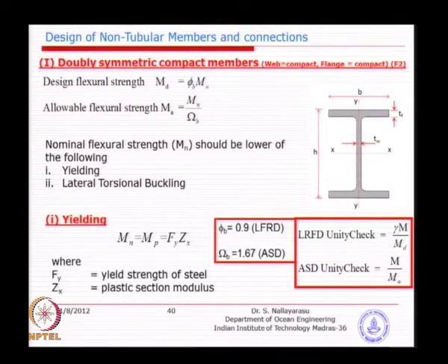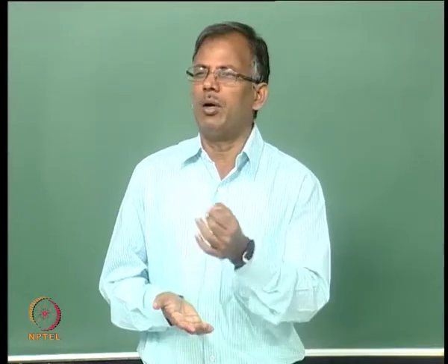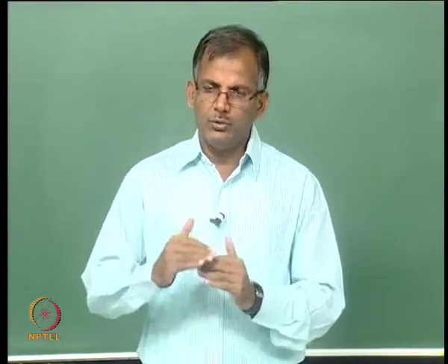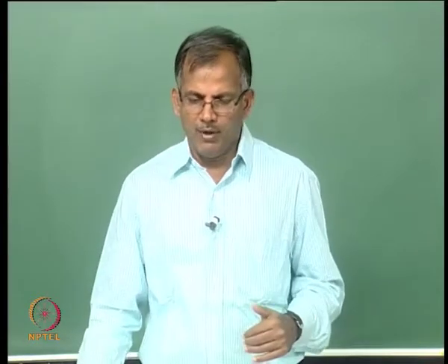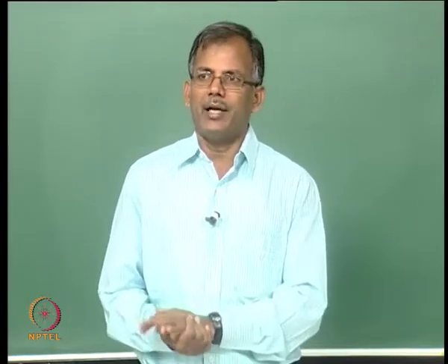So, major axis bending and minor axis bending, what is the difference? Suppose you put one more flange or one more web on these sides, then it does not matter whether this is the major axis or that is the minor axis, it becomes almost similar. But the idea we were talking about yesterday was to increase the bending in one plane, where large bending is there, while in the other plane bending is not there. Horizontal bending for deck structures is very small. That is why you maximize the bending, and what we are worried about is the major axis strength.